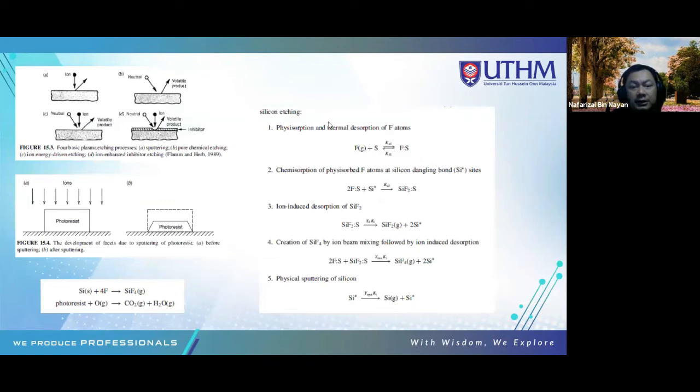Okay, again. This is another piece of information about the etching. The most basic process of the plasma is that the ions will bombard the material and remove the material. That one we call sputtering. And then we also have neutrals and volatile products that will do the etching.